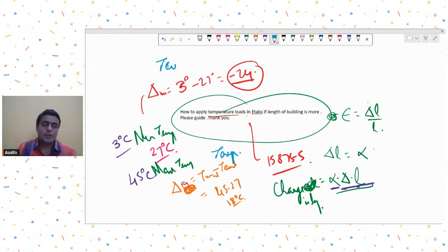The other load case you name temperature contraction, and then you assign these delta values to your members. Automatically the software is able to calculate the difference in length and accordingly apply those temperature load cases, and then you can include them in the load combination.